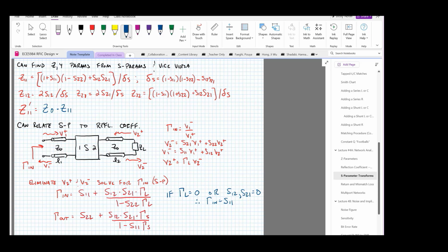When we make amplifiers, almost any passive circuit that we make is going to be reciprocal, which means that whatever S11 equals, whatever S21 equals, S12 is going to be equal to. But with active circuits, oftentimes we want it to amplify in one direction and do nothing in the opposite direction. So when we make amplifiers, oftentimes we're trying to make S21 big and S12 equal to 0. And what we're going to find is that this causes us tons of problems with stability if we aren't able to successfully do that. We can say the same thing for gamma out.